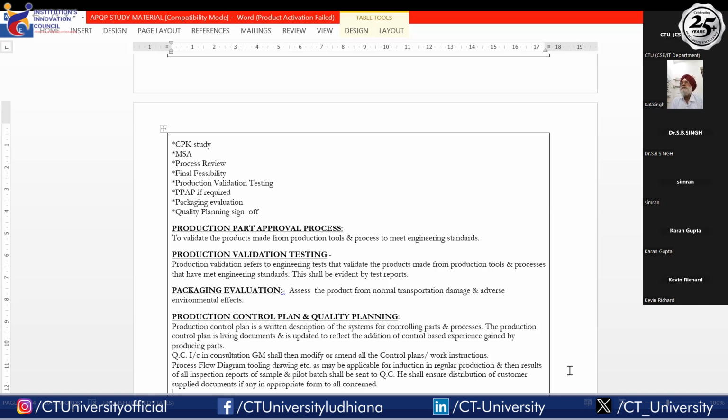Then after doing FMEA, whatever are the critical gaps or potential risks where some process or product can fail, we take precautions for that particular product or process. Then we design the process flow, make the control plan, and set the process parameters. We set the process parameters through process validation, which is done on that particular product by having different trials, and the best results given by any particular trial are frozen, and those parameters get standardized. So this is how a product or process is designed.